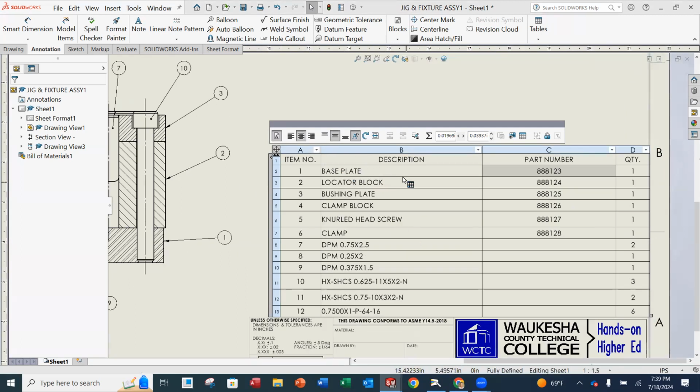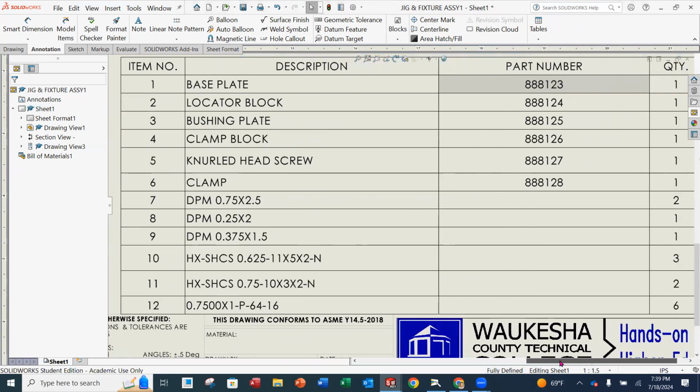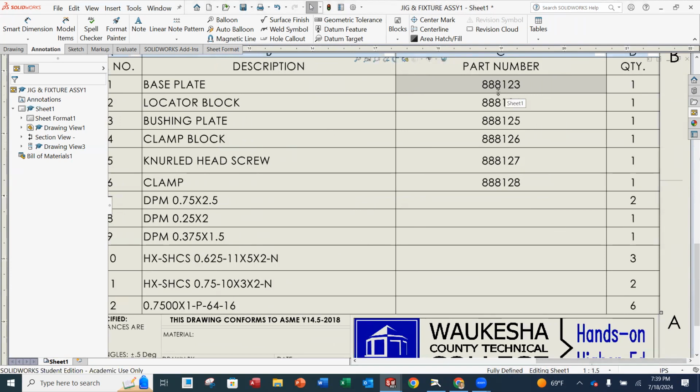The next thing that we want to do is we just want to make sure that all of our part numbers are good, but the ones that are down here, I'm sorry, the descriptions, the ones that are down here, we are going to be changing these because these are kind of like, I don't know, they're SolidWorks versions of the part number or the part description, and they're not easily gotten. So we're gonna change those to match what we have in the bill of material that I have down below. But before we do that, let's do the part numbers up here.